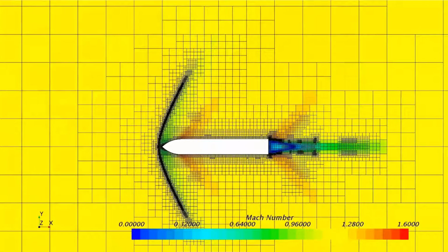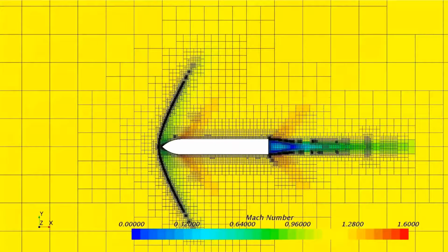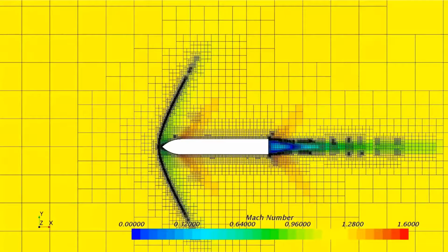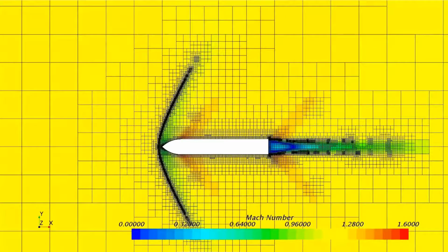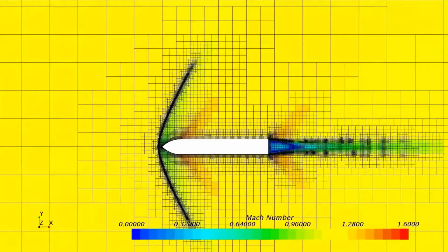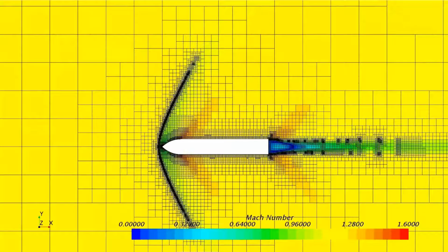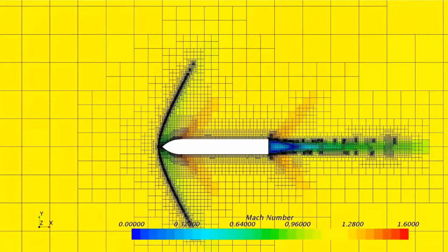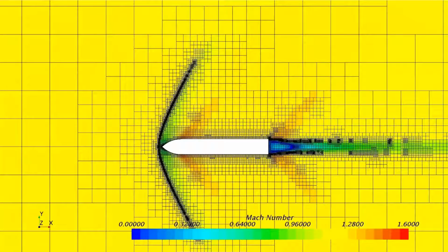And so you can see how the mesh tracks the shock and does a much better job of defining the shock and making sure there's enough mesh resolution across those high density gradients. I find this intriguing to watch, the way the cells in some areas seem to wane a little bit as they move along, and in the end it kind of stabilizes.